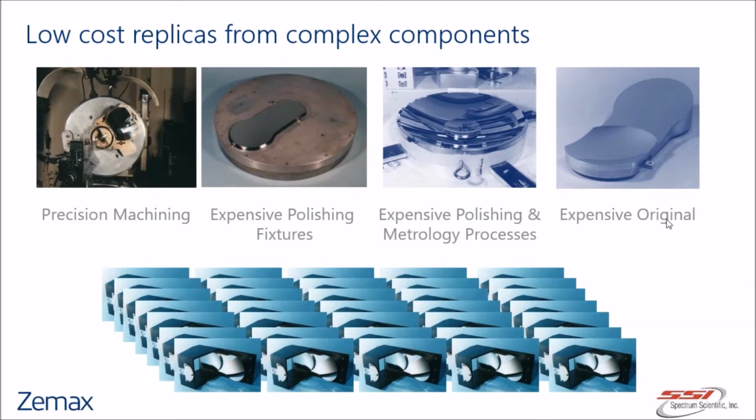It's then coated with a release layer in a vacuum chamber and a reflective thin film applied onto the release layer, and then a polymer is applied and the replica substrate is joined to the master. Then these parts are left to cure. Once they are cured, they are separated, and it's through this process that the profile of the master is transferred onto the replica substrate, producing a replicated optic that's virtually indistinguishable in performance from the original master, with excellent reflected wavefront and low surface scatter.